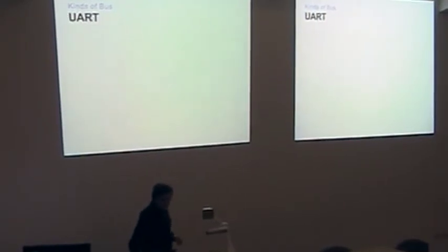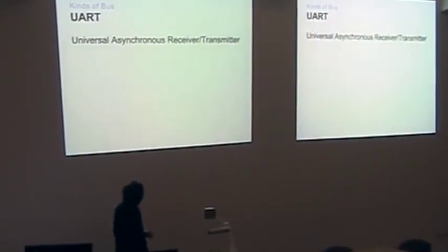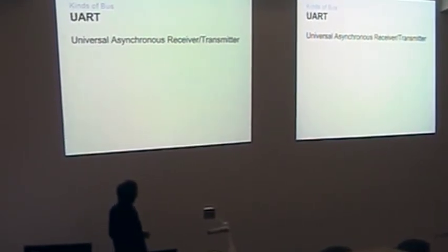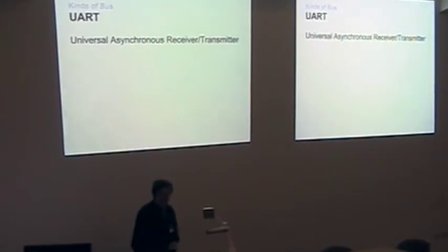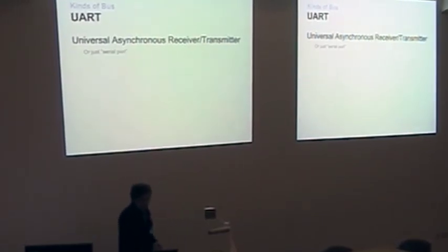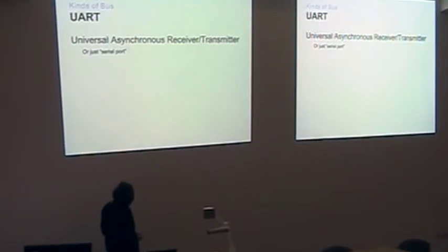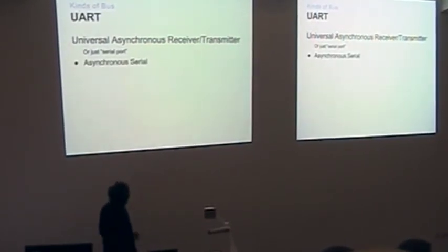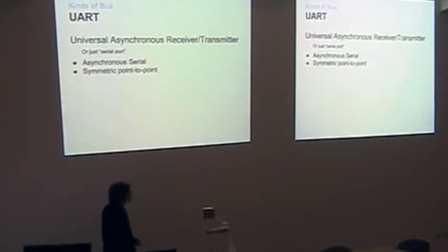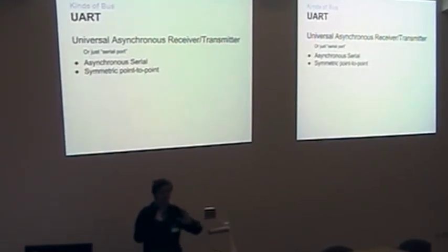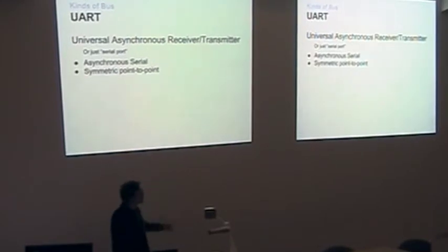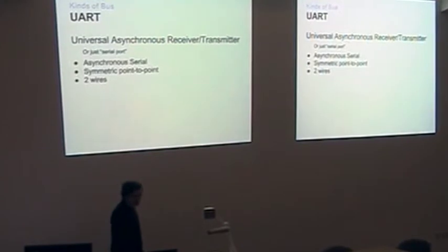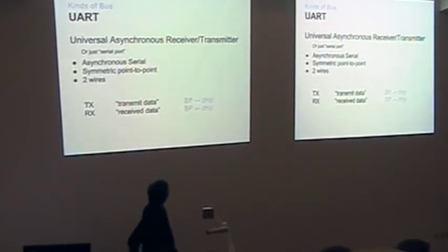And then finally, just for completeness here, I'll talk about UART, which is yet another exciting acronym that stands for Universal Asynchronous Receiver Transmitter, which again is almost meaningless. But the key word in there is asynchronous. I mean, most people just call it serial port. The key word is asynchronous because it doesn't have a clock. It's also symmetric in that you just have 2 ends that talk to each other, or maybe just one end. Maybe you actually only wire up one of them because you don't need to do anything else. You have 2 wires which are called RX and TX.